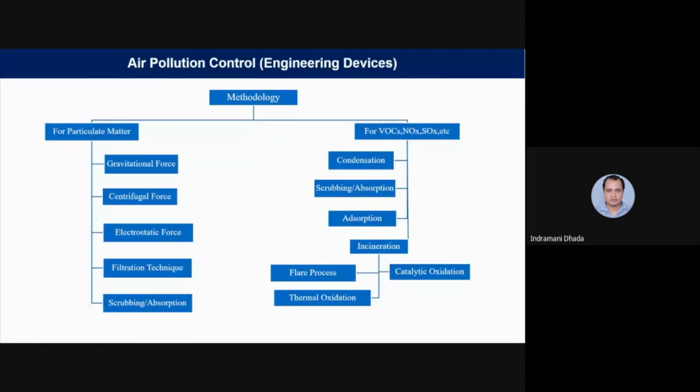For particulate matter, the mechanisms are gravitational force, centrifugal force, electrostatic forces, the filtration technique, and then scrubbing or absorption also. For gases like volatile organic compounds, NOx, SOx, etc., there is condensation, then scrubbing or absorption, adsorption, incineration, then flare process, thermal oxidation, catalytic oxidation. What are those things? Well, we should know; this is the basic thing.